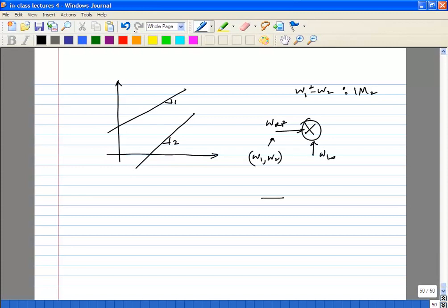Remember, we model the mixer as something like this. There is a transconductance followed by the real mixing, which is the switches. So this one is the one which has nonlinearity. This one we don't care about, it is just a switch. We modeled it as the signum function, right? So most of the nonlinearity actually comes from the transconductance. Okay, so if you put in 2 tones, at the output here you are going to get omega 1 plus or minus omega 2 and that will get mixed down.